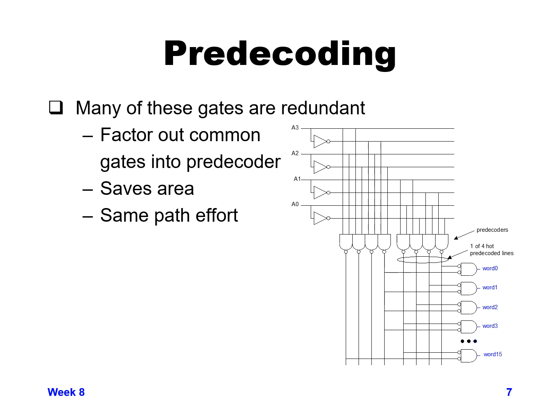So what we can wind up doing is, instead of having 2 NAND gates for each word, which gives us a total of 16 times 2 is 32 NAND gates, we can do some pre-decoding where we look at the lower 2 bits, for example A0 and A1, and create 4 combinations of A0 and A1 with 4 NAND gates, and then create all 4 combinations of A2 and A3 with another 4 NAND gates, and then we tap off from those pre-decoded values to go into the NOR gates for each of the 16 words.